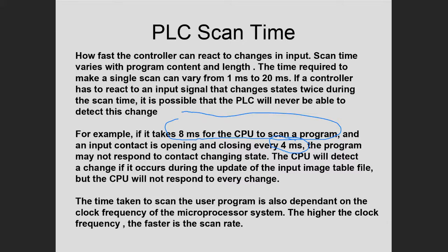So mark this slide and understand what I mean by scan time and know what kind of problems can arise, or know when it can be a problem. It can be a problem if you have some device with a frequency of something happening faster than the scan time of the PLC. Data can be missed.